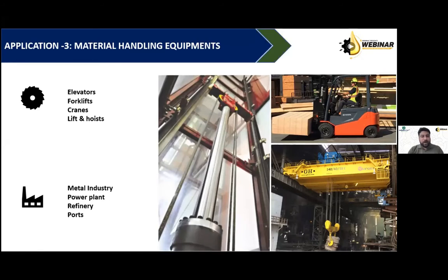If you talk about a power plant, there you have bulk handling equipment, and these bulk handling equipment are in the place of coal handling. There you have multiple equipment for handling of coal, for example, the wagon tippler or the sidearm charger or stacker reclaimer. All these equipment also work on hydraulic principles, and complete systems are hydraulics. The reason is hydraulic can handle precise motion, as well as it can handle large amount of force when you have to provide certain motion.